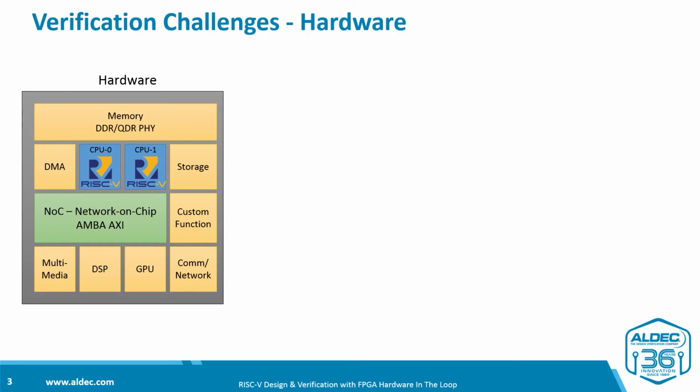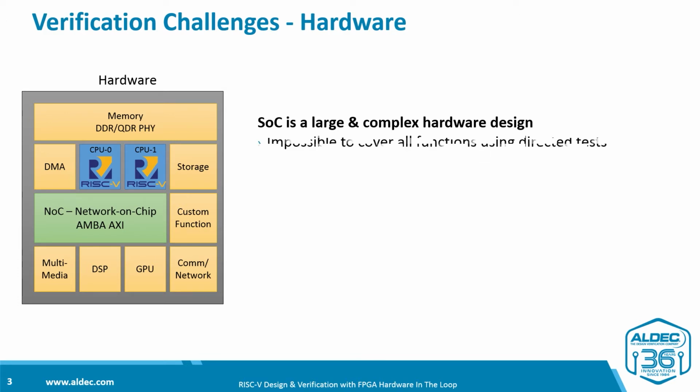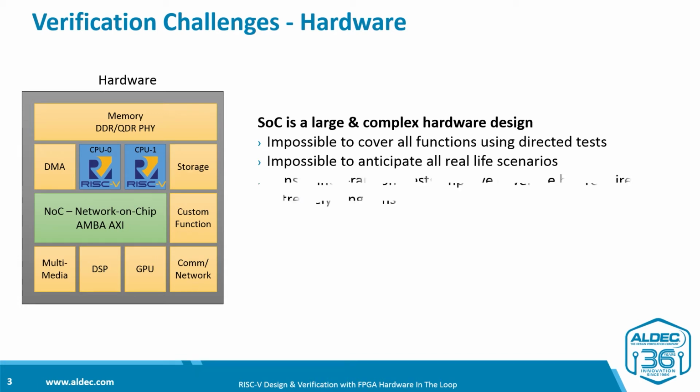Hardware part is a complex design by itself. Current designs are heterogeneous multi-core architectures with lots of subsystems and peripherals interconnected by hierarchical networks on chip. And traditional test bench methodologies based on directed tests cannot cope with this complexity. It's impossible to cover all functions with directed tests. Actually, it's not even possible to anticipate all possible real-life scenarios.